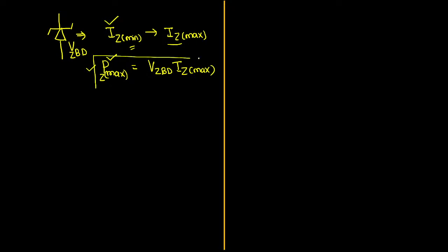So in the examination, if they ask you to identify the maximum power consumed by the Zener diode, you have to identify the maximum current carried by the Zener diode. Remember one thing: the current goes from cathode to anode, not anode to cathode, and we have also highlighted the polarity very clearly. So this current is called Zener current. Now you have to decide whether this Zener current is maximum or minimum according to the given question. Okay, I hope you all understood.